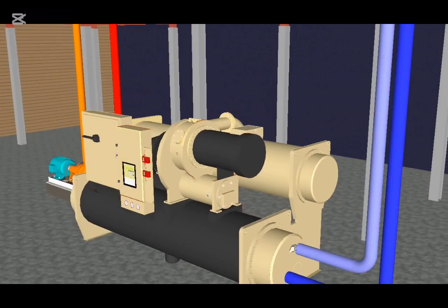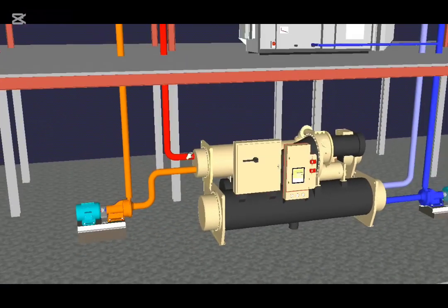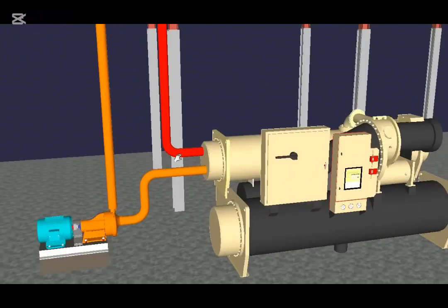So now that the heat in this pipe here has been transferred over to the condenser side, the condenser then sends this water, which is now called the condenser water, up to the tower. In this instance, I've coloured this pipe red so that you know it's a higher temperature, and in this example it's about 35 degrees Celsius, at a flow rate of about 58 litres a second, being sent up to the cooling towers. That can change, as this design is just for illustration purposes.